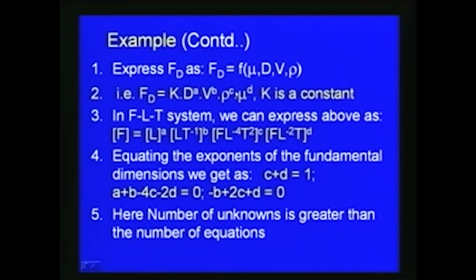Now, as I mentioned, we can use either mass, length, time units or force, length, time units for the dimensional analysis. Here we are dealing with the drag force, so let us solve this problem using the FLT system, the force length time system. The drag force has the unit of force, so we can just represent it as F.